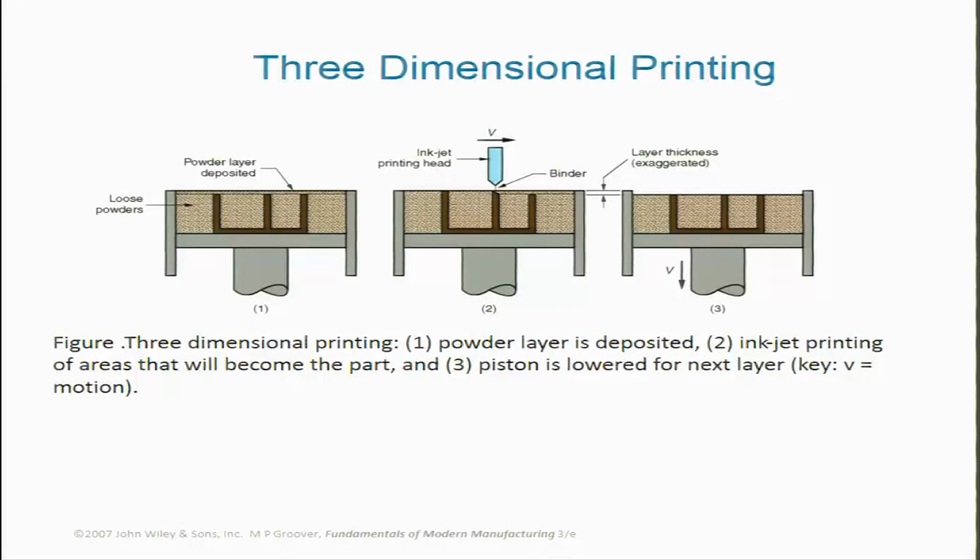So, this is how it would look. You have a powder layer deposited, okay, and then there is an inkjet printing head which dispenses the binder material in certain zones, and wherever the binder material is deposited, they are solidified. So, this part, for example, has been solidified. This is in the process of getting solidified. Here again the binder would be deposited, so this part gets solidified. The remaining is again in powder form, can be brushed off or brushed aside, and you can generate this whole bound powder form of part, okay, in place.